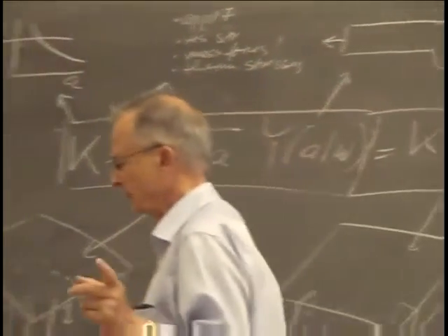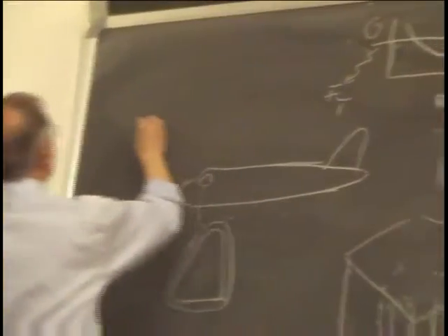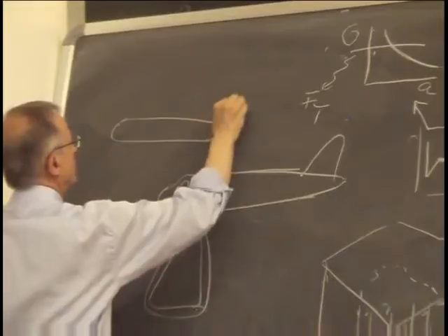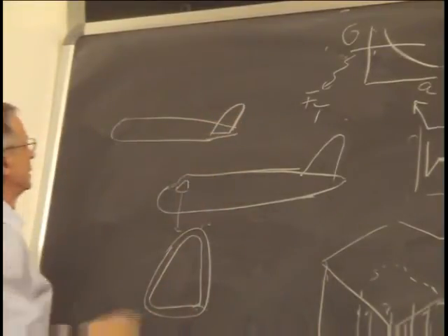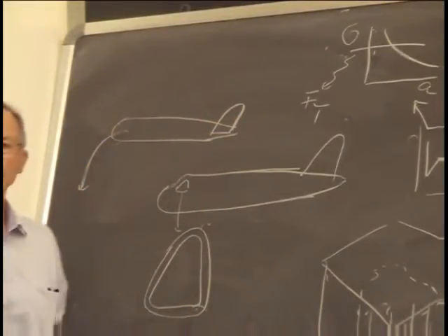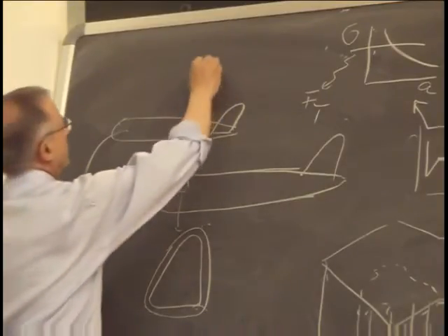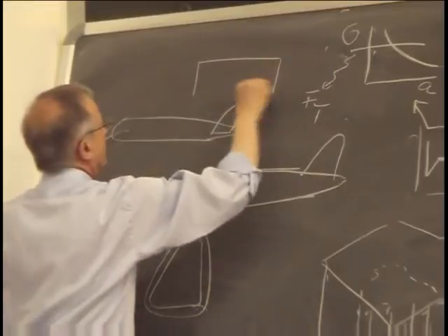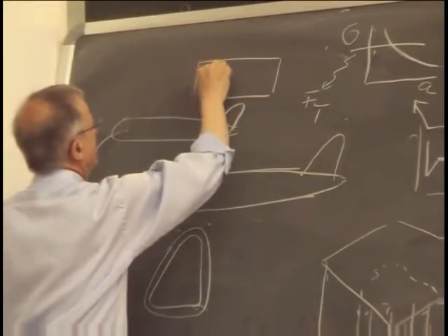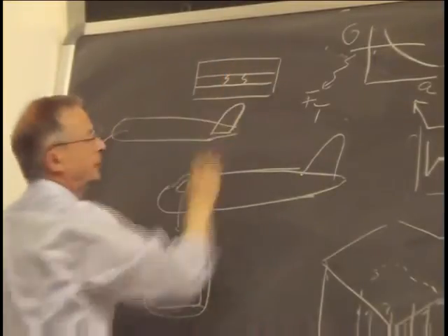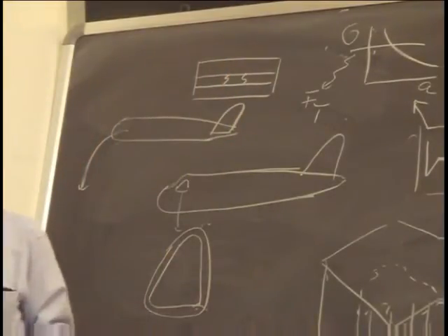And the Lusaka crash that I also mentioned was an aeroplane where here the balancer broke, so the whole thing went nose down. Fortunately, it was only a freight plane, so there were no passengers on the plane, but the crew died, of course. And in that case, the crack initiated in a piece of a built component, and it was not accessible to inspection.